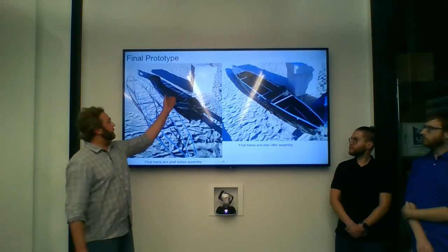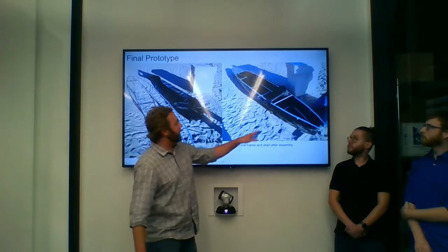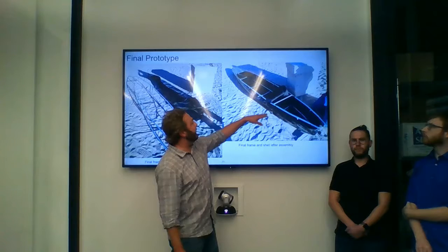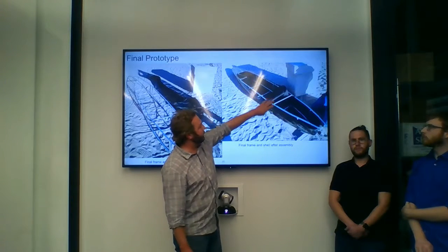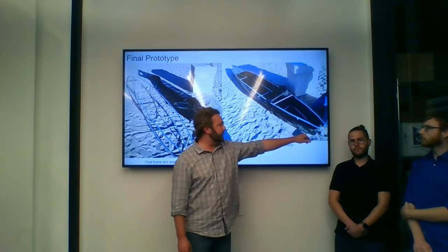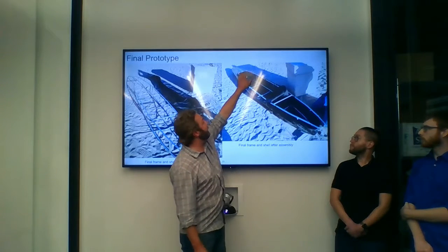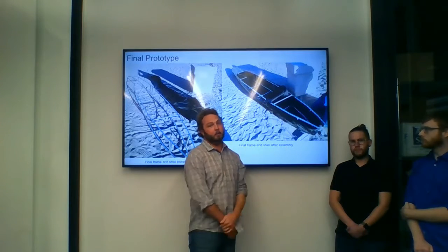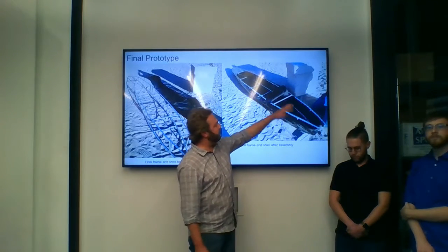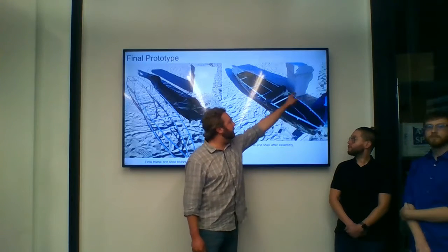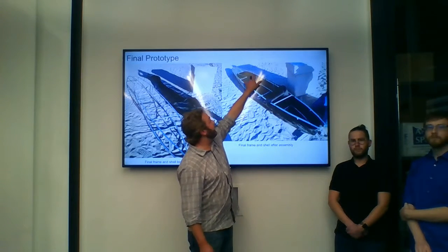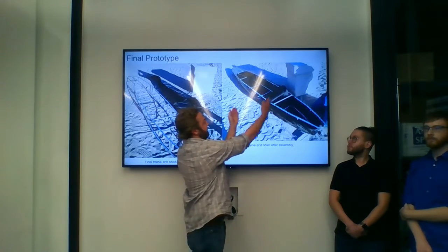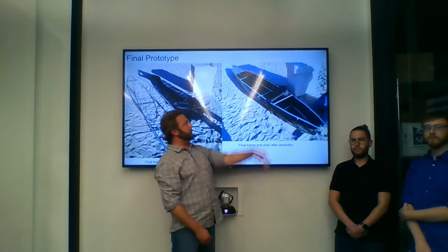Here's our kayak frame, here's our final shell assembled, and then the way that we would put the shell onto our kayak is we slid the back through this opening past the end of our shell to the point where the nose could slide in there, and then slide it back, pull the shell up around the stern of the kayak, and then this flap flaps over and a zipper zips around, and then we have straps here and here that strap together. That way, when you have the buoyancy force acting on the bottom, it doesn't pull the sides down, and the seat sits between those two straps.